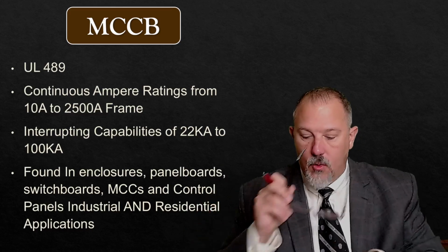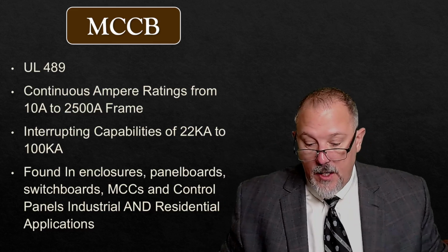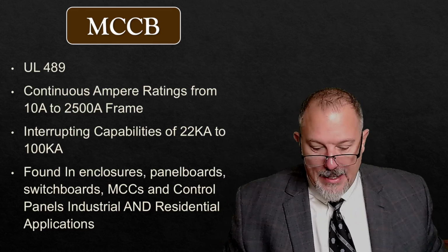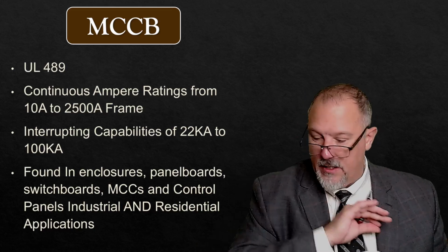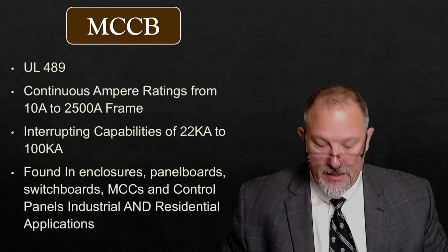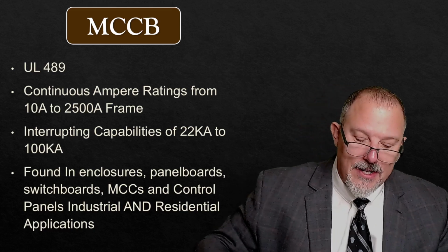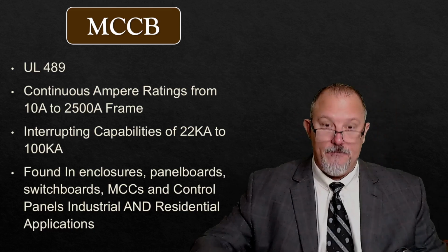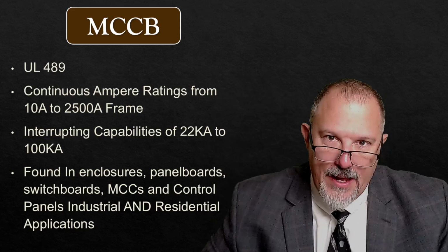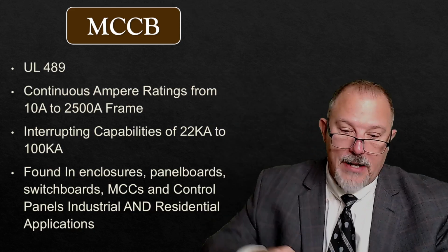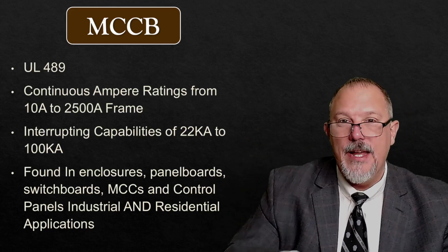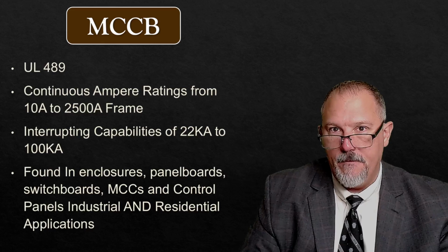We're going to be in Article 130 within this wonderful resource for life-saving concepts and ideas and requirements. Table 130.7(C)(15)(A). What is that table within the NFPA 70E safe work practices? This is our PPE category. We call it the table method.